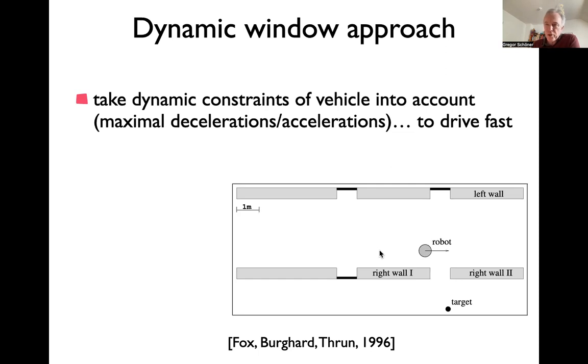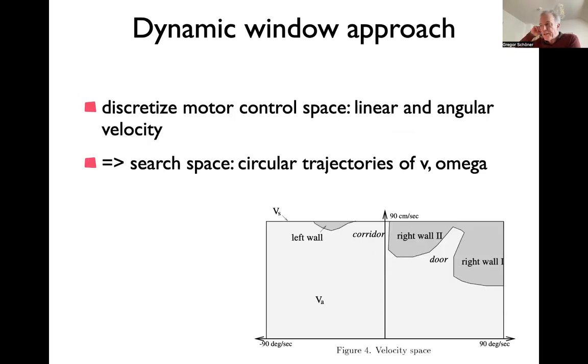The last moment means braking such that you can still make the turn. And so what they do is essentially define surfaces in velocity space that are forbidden given the sensed layout. So you still have conventional sensing, some distance sensor, that gives you from the current vehicle point of view a contour in the world, and then they translate that, given the current velocity, into constraints for velocity. The constraints are computed by asking: with that velocity and that distance I sense there, can I still stop before I hit that?